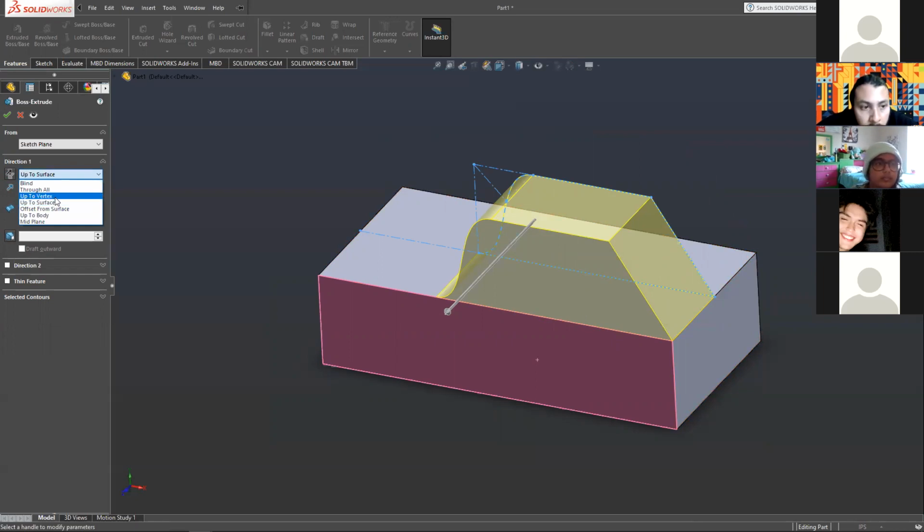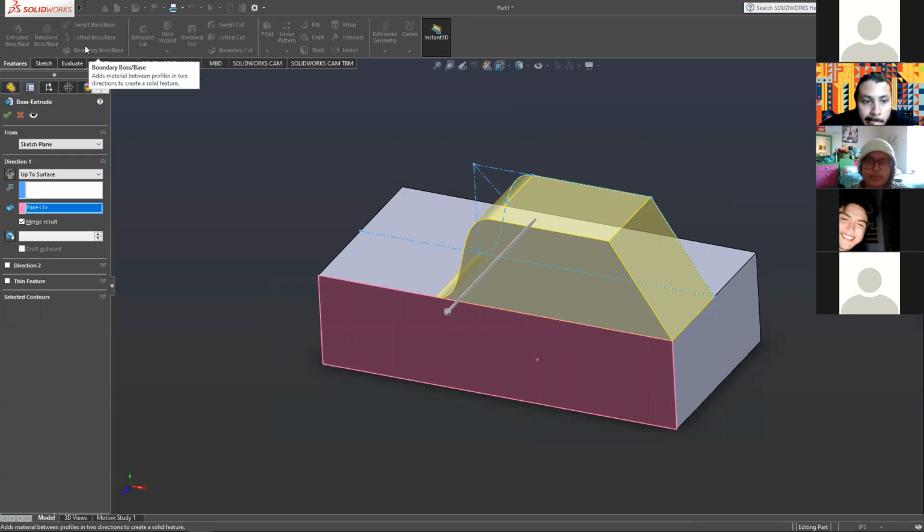We extrude it by selecting sketch 2, and then you go to extrude boss base in the features tab. Oh, okay, features. Yeah, go back. Features tab. Sketch has its own tab, and then the features is like taking everything to 3D. Okay. How do you edit a thing if you've already pressed enter?